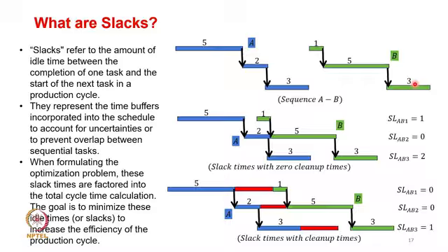See, stage 1 of B only takes 1 hour, but stage 2 of A again takes 2 hours to complete. So you have to wait until it is over; for this production, you can only start after 2 hours. So there is a slack of 1 hour in stage 1, because stage 1 of B requires 1 hour, but stage 2 of A is only free after 2 hours.